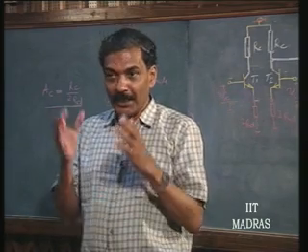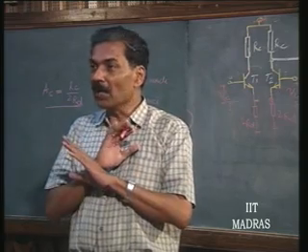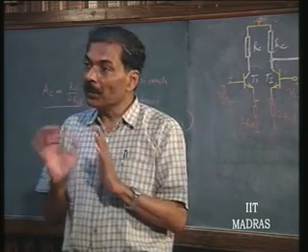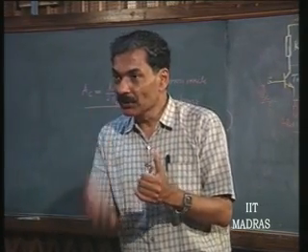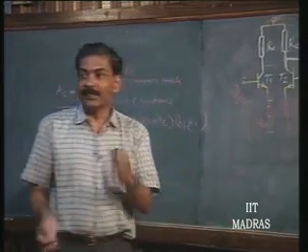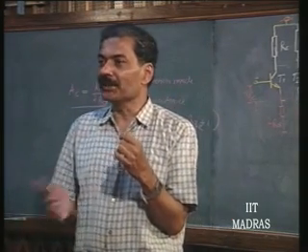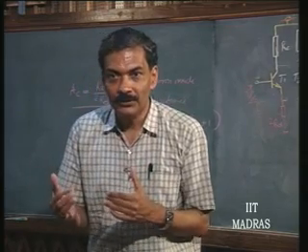Yes, the entire differential mode of operation has come about not due to output at all. Please have that very clearly in mind. It is only due to the input arrangement of having a current source here that is responsible for the differential mode. How you are connecting what at the output is of no consequence. That is what I am trying to make clear to you.